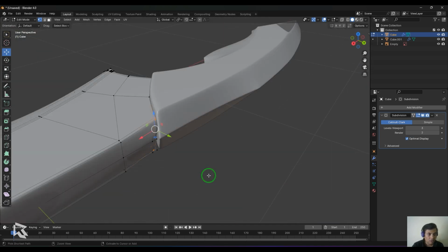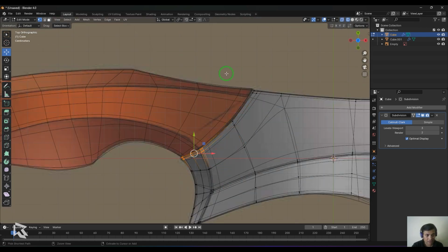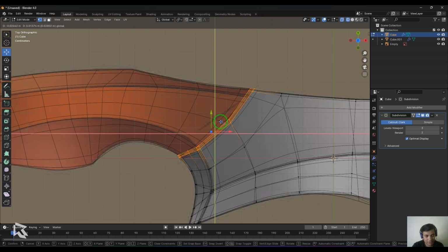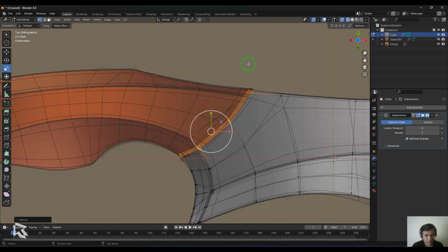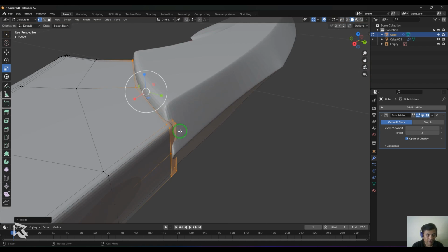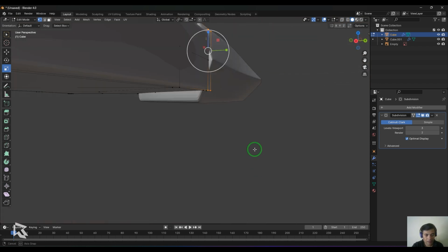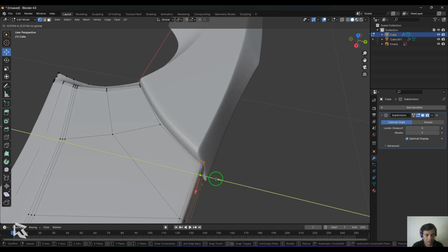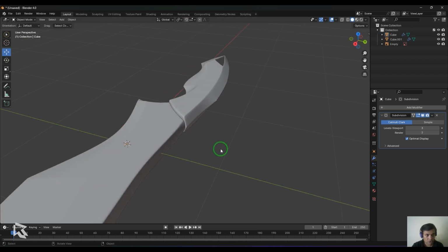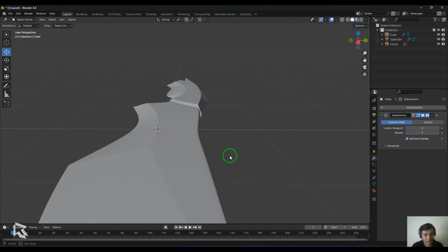If anywhere you feel that penetration is not happening, you just try to fix it like that. So I just go a few steps back here, because the problem was that I need to press Shift Z to select, because in the shaded mode it doesn't select the backside faces. That's something I need to take care of, and something a bit special about Blender. So you should see I couldn't select those points. Once we penetrate it, you get a nice connection there.